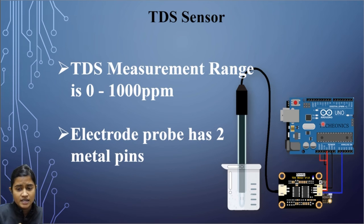A TDS sensor is basically a small handheld device used to indicate the total dissolved solids in a solution. Since dissolved solids such as salts and minerals increase the conductivity of a solution, the TDS meter measures the conductivity of a solution and estimates the TDS from the reading. So how does it work? A TDS sensor is basically an electrical charge meter whereby two equally spaced electrodes are inserted into water and used to measure charge. The result is interpreted by the TDS meter and converted into a ppm figure.